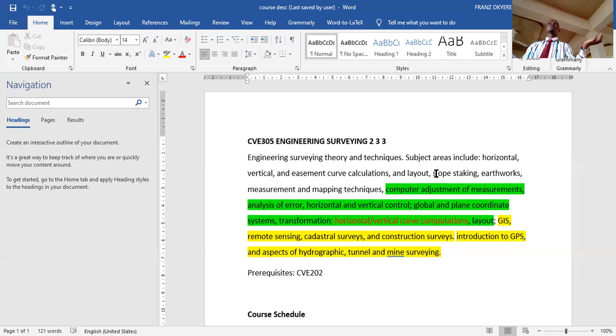Why are controls important? Generally, why are controls important? Once you set up on one control and you measure to another control, that becomes like a backsight. Then you turn to your foresight, and you start measuring or working from that. If you want to set out this building, you need a control. As an introductory lecture, why do we need control as engineers?